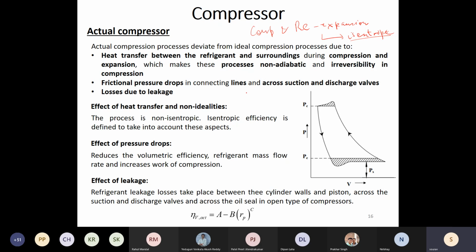So in your reciprocating compressor, you have two valves, one valve which opens inward into the cylinder. This is the movement of this valve, goes down and back up, whereas another valve is moving on the outside of this. So these are the two valves which are placed on your valve plate.